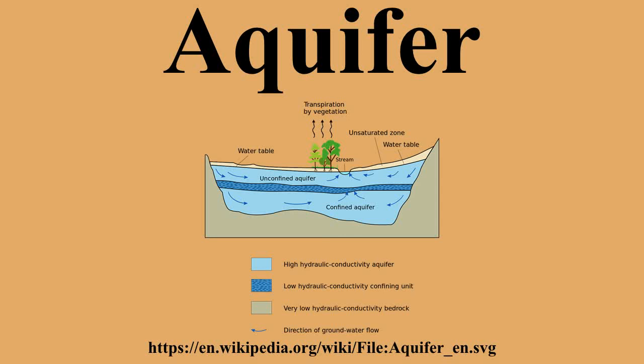If a rock unit of low porosity is highly fractured, it can also make a good aquifer, provided the rock has a hydraulic conductivity sufficient to facilitate movement of water. Porosity is important, but alone, it does not determine a rock's ability to act as an aquifer. Areas of the Deccan Traps in west-central India are good examples of rock formations with high porosity but low permeability, which makes them poor aquifers.